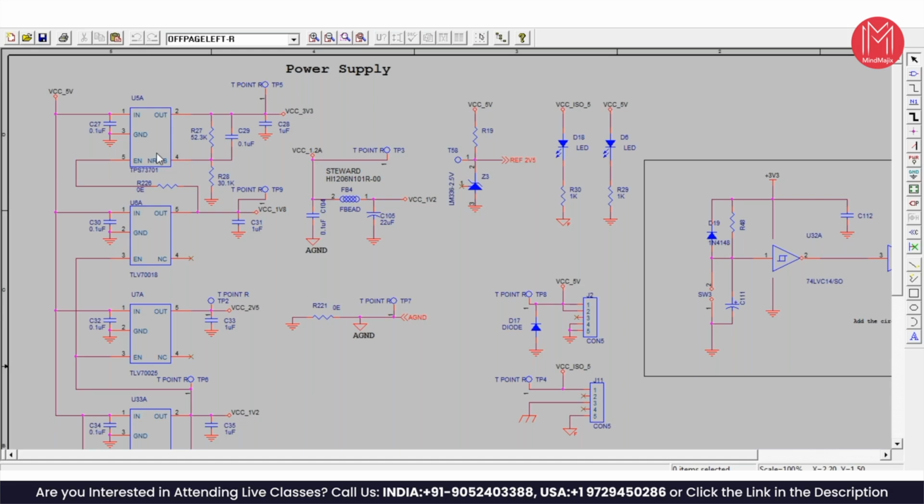Sometimes if we want different outputs, we can design R1 and R2 according to our need, that's what we're saying, right? Correct, exactly. So let's say we want a 1.8 volt output derived here. We calculate R1 and R2, here R27 and R2. Then we put those according to that, like you showed earlier. Yes, correct. And what about the capacitor value?